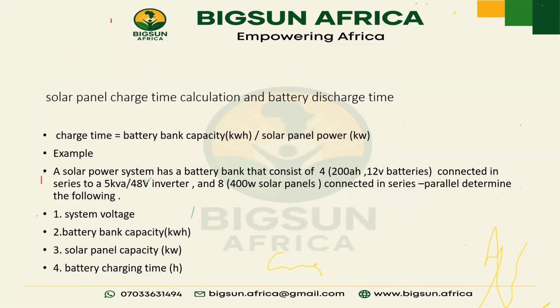Okay, so the battery charge time now is going to be 3 hours. How do you get 3 hours? 9.6 kilowatt hour all over 3.2 kilowatt. That's going to give us 3 hours, right?